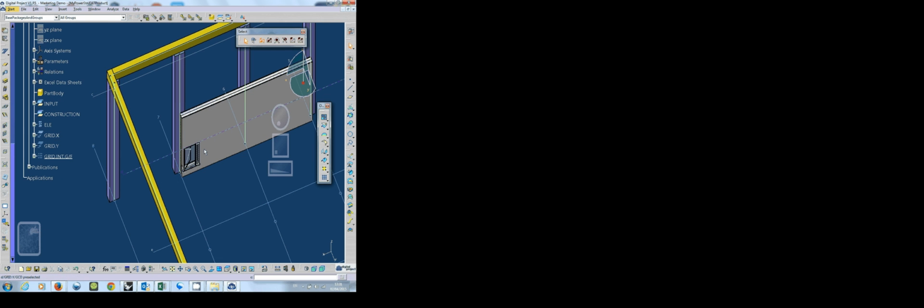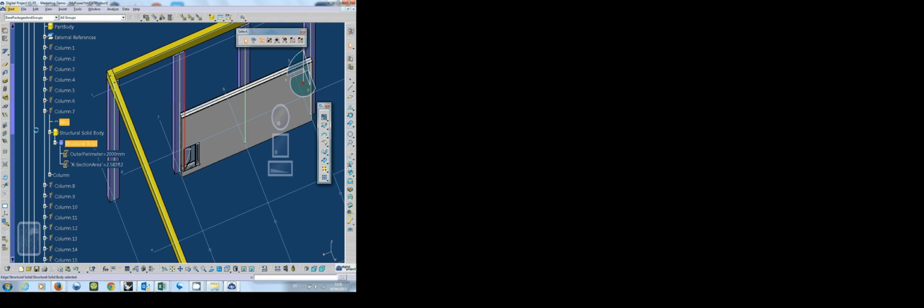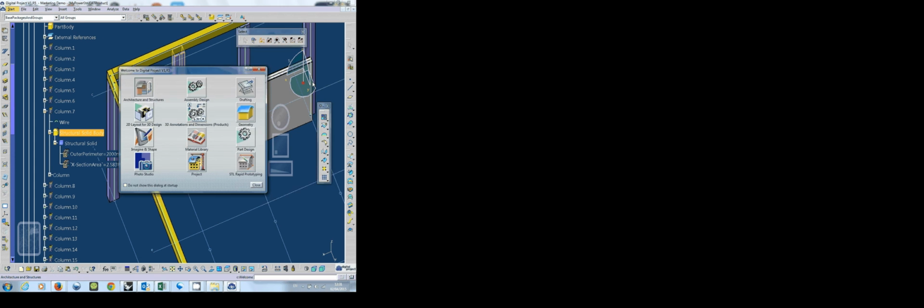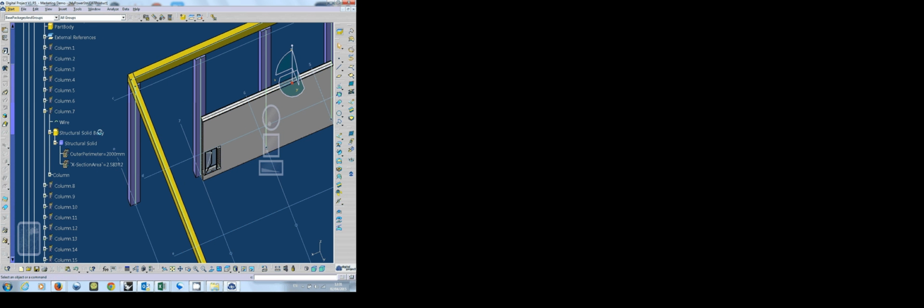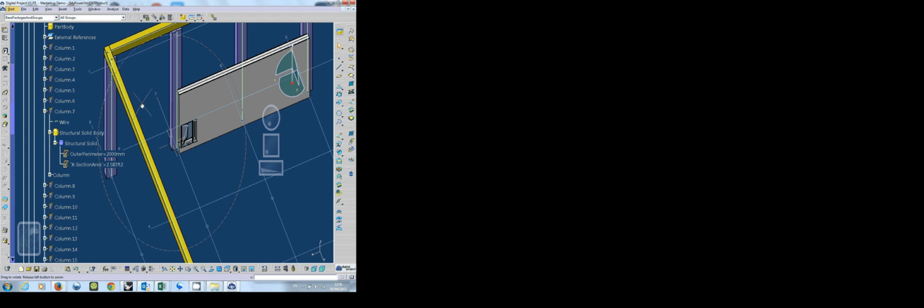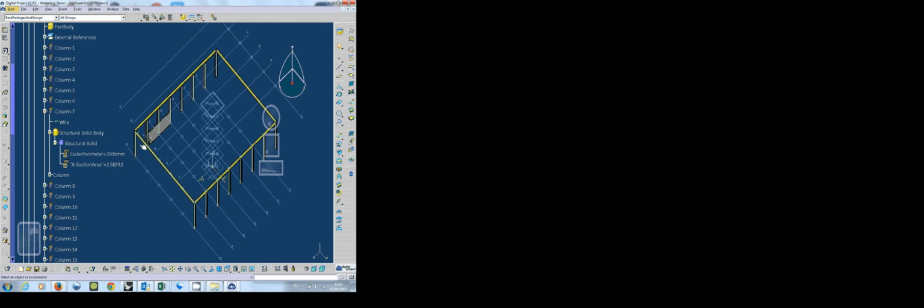One more last thing, this object, in fact, if I look at it, contains a number of objects, including a solid, which means if I go to the geometry, you can still modify it as if you operate on a solid. So you can pocket it, you can delete, you can add some additional features to make the column not just an extrusion. Okay. So this is something I introduce for you to look at, using the architectural workbench for the assembly idea.